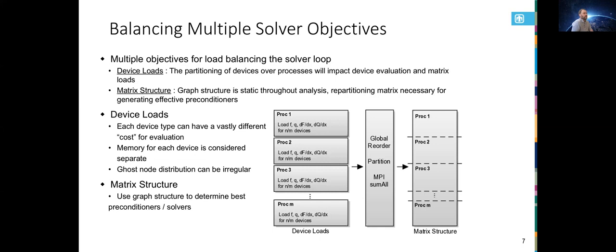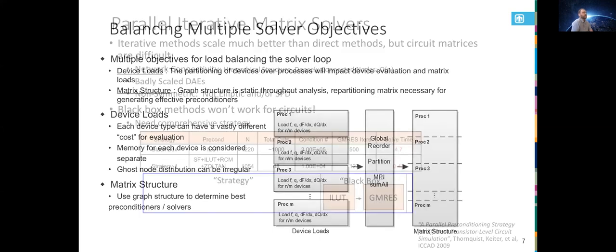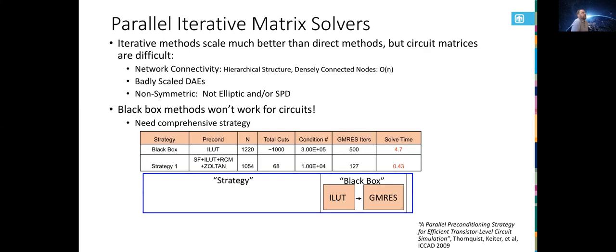As far as getting matrix solvers to work correctly for circuits, another detail I could have mentioned earlier is that most SPICE simulators use what are known as direct methods to solve their matrix, which basically means they're doing something like Gaussian elimination. That method will give you a fairly precise answer, and it's very robust, but it tends to scale very poorly. Even the most advanced direct methods start to bog down like crazy once you get up into the hundreds of thousands of unknowns. So if you're going above 100,000 unknowns or so, direct methods don't work so well.